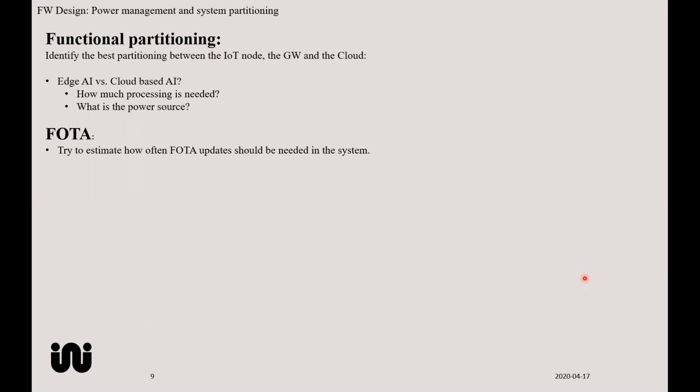When you do FOTA updates, and every sensor today should implement firmware update over the air, this is supported by Bluetooth Low Energy, Bluetooth Classic, Wi-Fi, what have you. So FOTA needs to be considered. Already when you systemize the device or the system, you need to understand how often you should do FOTA updates. There are different reasons to do a FOTA update. One could be bug fixing, and by nature it is quite common to have more bugs in the early days of a release.